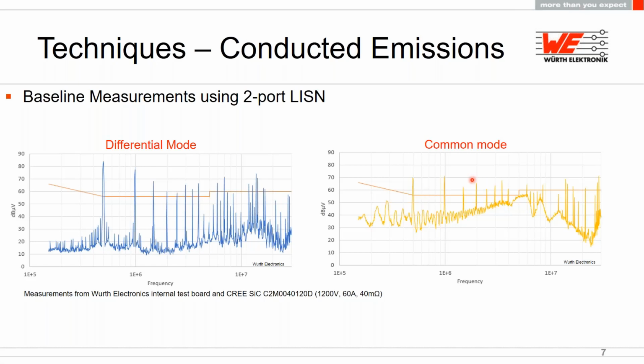Common mode, even in the conducted band, we do have common mode noise. And we do even have it at these peaks. Most people wouldn't think that. They would think that it would be an entirely differential mode issue, but you can see that due to the parasitics on the board, you do get some common mode noise as well at these same peaks. Of course, overall, the base of this is much higher because there's other circuitry on this board which is affecting that and causing all these other peaks up in this 10 megahertz range.